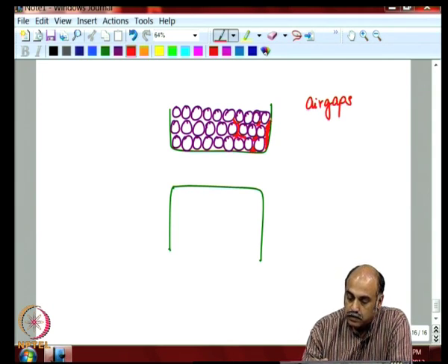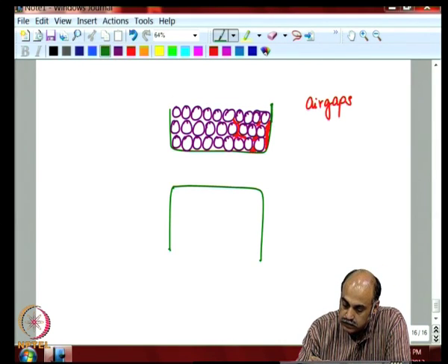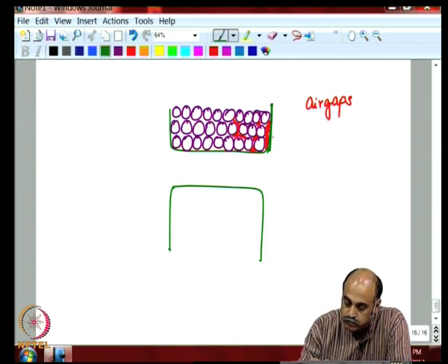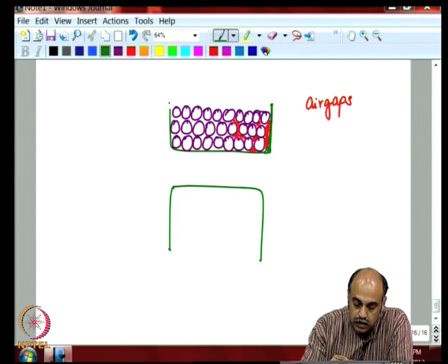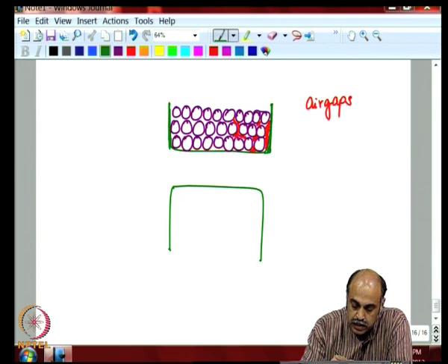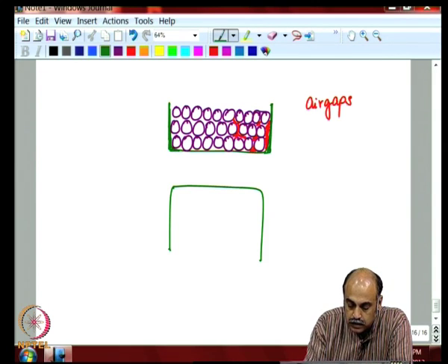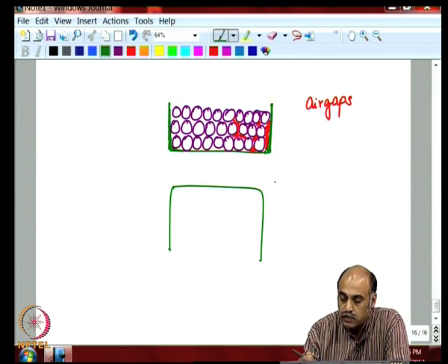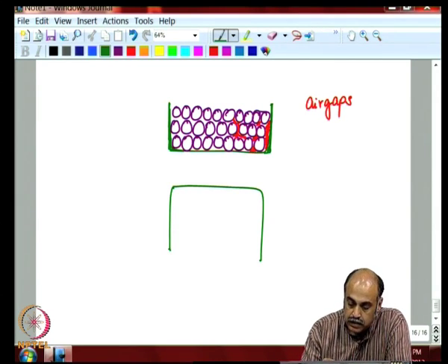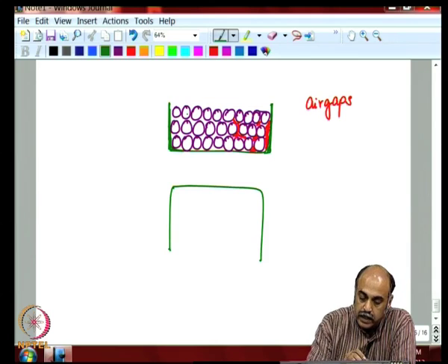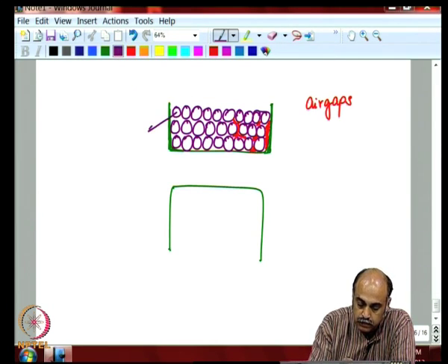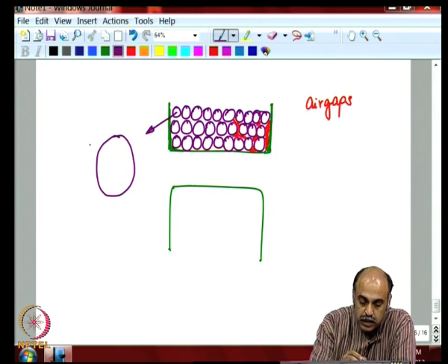There is also the thickness of the bobbin itself, which is eating into the window area space. The thickness of the bobbin, the air gaps, and this wire itself all eat into the window area space. If I blow this wire up, this cross section has two parts.